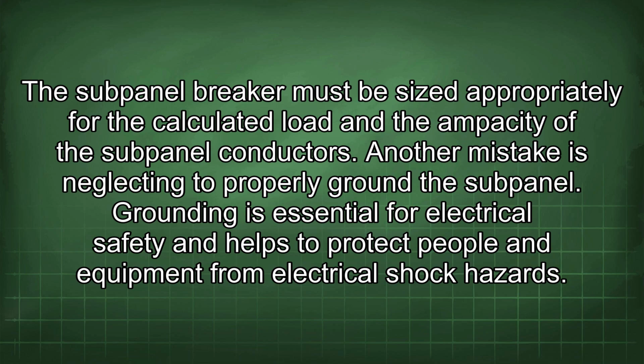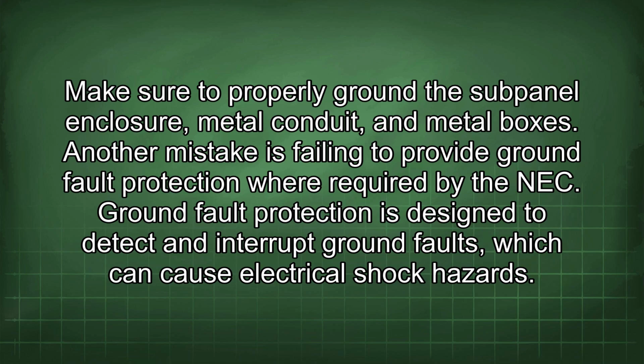Another mistake is neglecting to properly ground the subpanel. Grounding is essential for electrical safety and helps to protect people and equipment from electrical shock hazards. Make sure to properly ground the subpanel enclosure, metal conduit, and metal boxes.